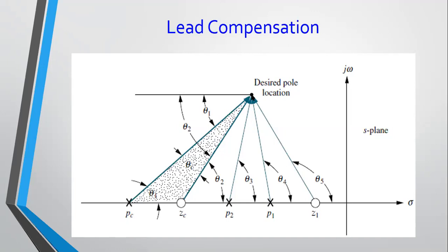root locus. So basically what you are providing here is a θ2, if θ2 is the angle the controller is providing. Now if you were to add, in addition to this 0, a pole as part of controller design, it means you are also introducing an angle θ1 here. So θ2 is from the 0 and θ1 is from the pole. So the difference of the two is very nicely shown here.